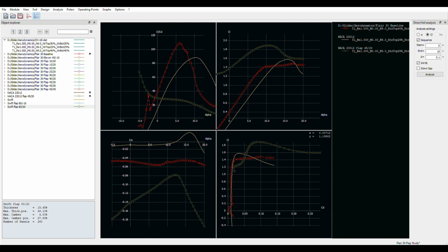No, we make a quick jog to the right, and then the CL goes up as the CD goes up. So it really ruins my performance. My L over D goes way down here. You hinge an airfoil much forward of 20–25% of the chord, and you ruin the performance of that airfoil.